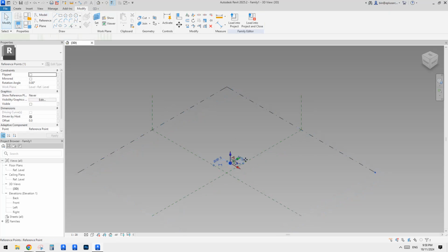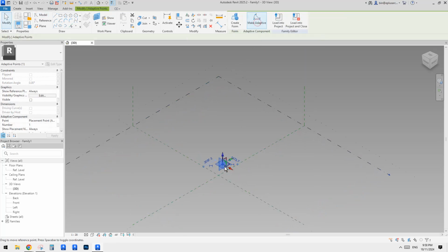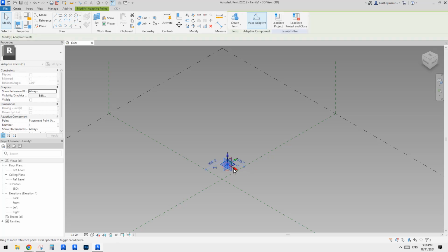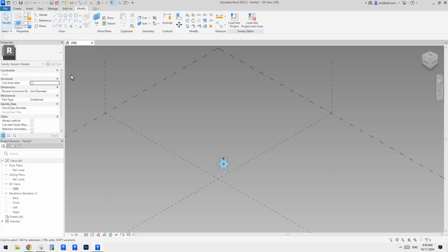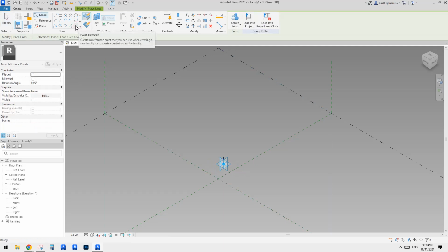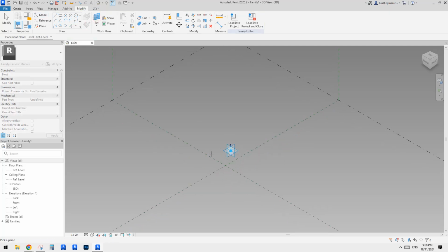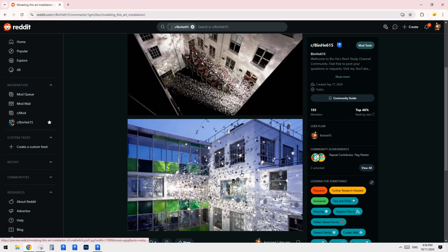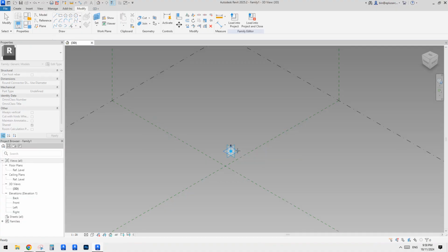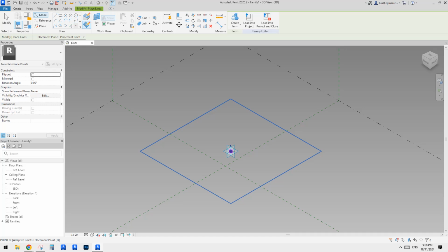I'll first place a model adaptive point, and then we can just start to place a point. So let's use the point and draw on work plane, set work plane. Eventually this one will be vertical, so we will take the box always vertical. Imagine these ones will be placed onto that cable, so it will place onto this horizontal work plane and then place onto the point.